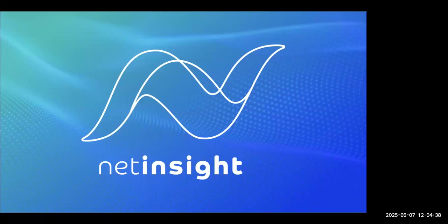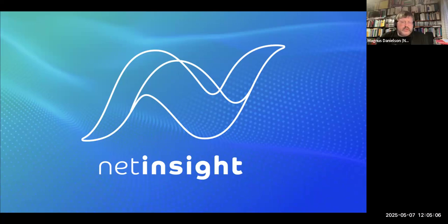Magnus, great presentation. I did have a quick question. I couldn't tell from the slides. Are you using the Raspberry Pi? Some of them have PTP support, and they do it at different levels. I think it's only the CM4, if I recall correctly, that actually has it in the Ethernet MAC. And with the Raspberry Pi 5, they do it further up, I think, in the RP1 or whatever it's called. But were you using any of those features, or was this just 100% stock Linux doing software-based PTP? That's stock Linux on a Raspberry Pi 5.